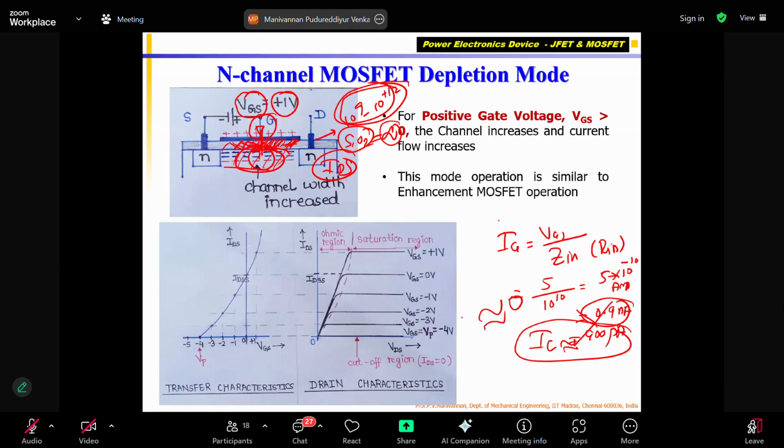Right? That's why we say it is a voltage operated device. Literally speaking, there is also some current. That current is so small, you can neglect it. So if I vary my gate voltage from 0 to 5 volts, my drain current will vary from 0 to 100 amps without taking any gate current. That's why it is called voltage operated: FET, MOSFET and IGBT.